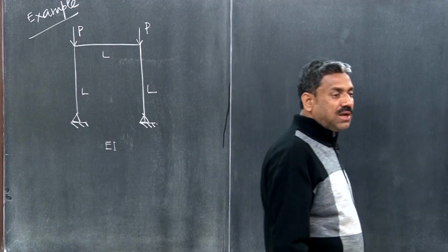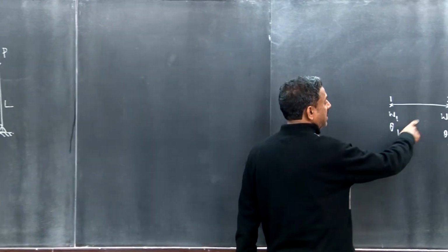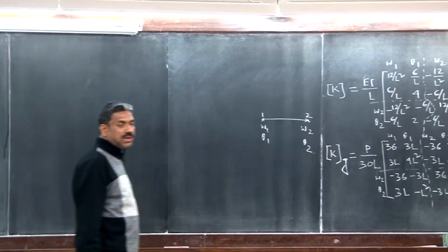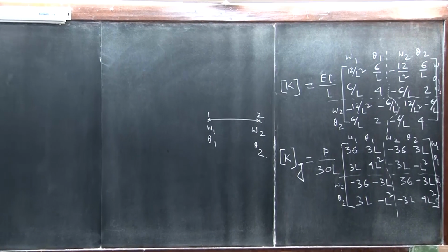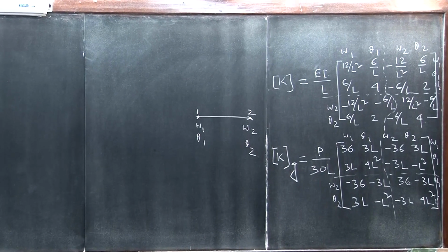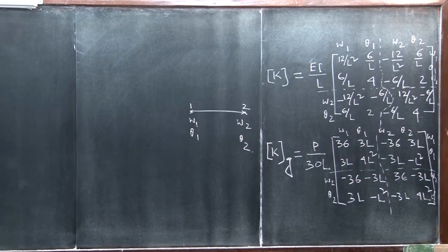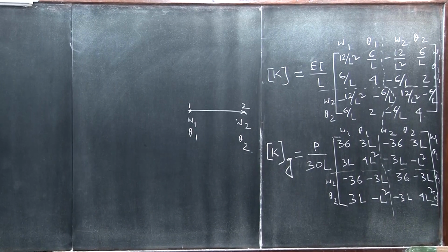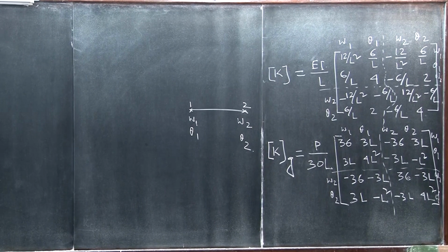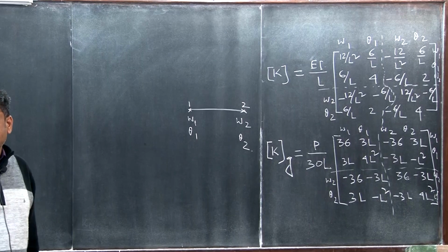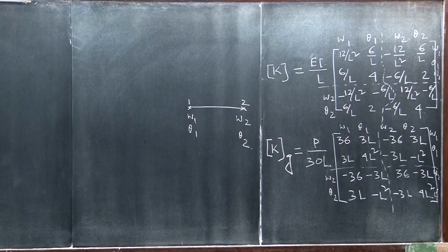With a single element discretization we can solve for its critical load. We solved that, and we saw that what we obtained by solving the algebraic eigenvalue problem matches well with the one we derived analytically in our second year strength of material class, right?